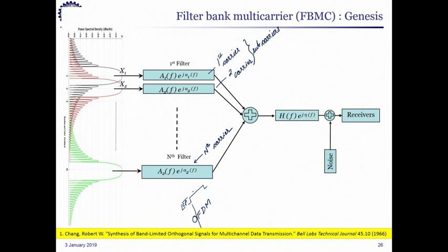So, amongst several reasons why these are considered are the OFDM, because of its rectangular pulse shape in time domain, in frequency domain generates a sinc, which we also had mentioned. And the sinc function, as you know, has pretty high side lobes. So there is adjacent channel interference which is pretty strong, but the good part is there is orthogonality. But again, the reverse side of things is that if you lose orthogonality, then there is a big problem, and that is one reason which gave rise to adaptive subcarrier bandwidth or variable subcarrier bandwidth, which got the name numerology